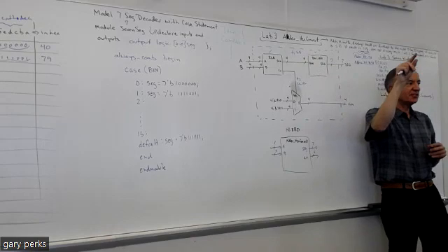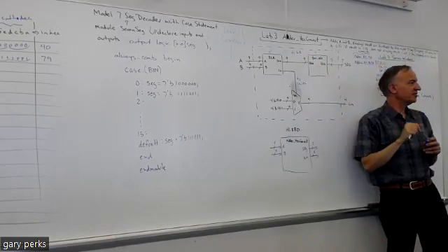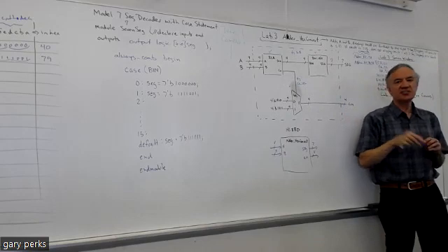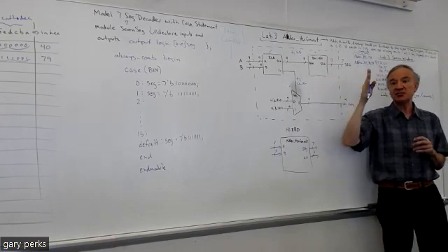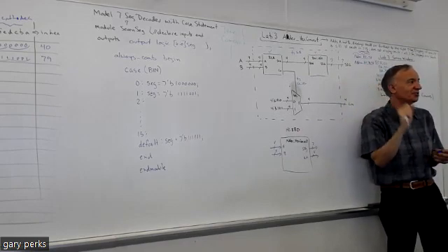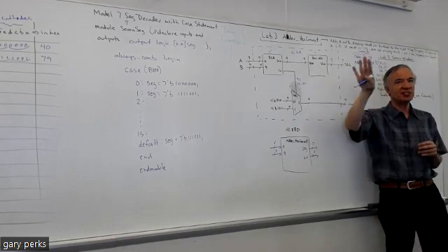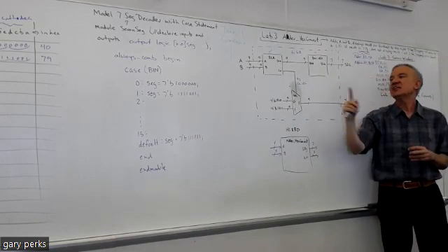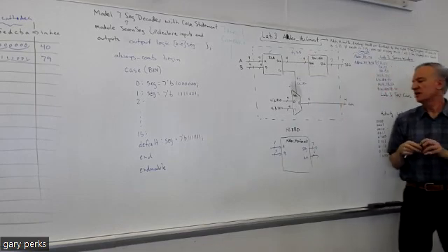So you'll have to do like the 3 to 0, whatever you call this. It's just like when you have multiple bit inputs and outputs, when you have multiple bit internal signals, you got to tell the software it's multiple bit. That's a common mistake: people will just put their internal signals as a single bit. And then of course the overall thing doesn't work.